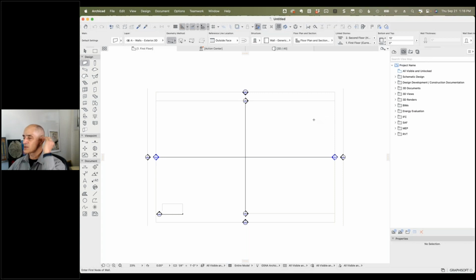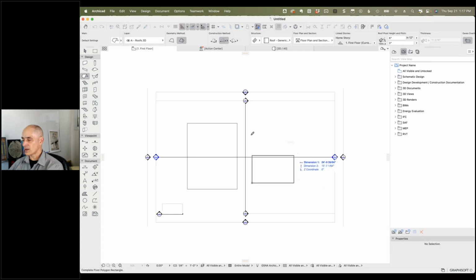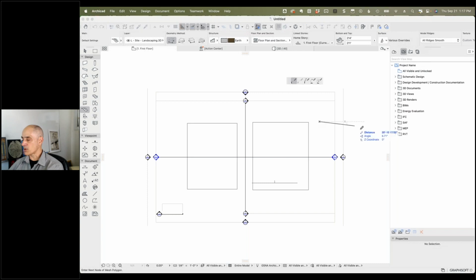Okay. All right, so let's just take a look at a couple of contexts here. Obviously, if you have the slab tool, I'll just draw this flat top and bottom, whatever thickness you want, one component or multiple skins representing framing and cladding and things like that. We have the roof tool, which has a slope, and then we have the mesh tool here, which will have some arbitrary boundary, any shape you want, and starts out flat, but can be graded.